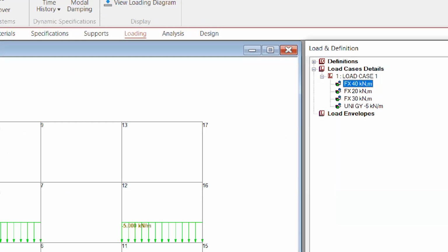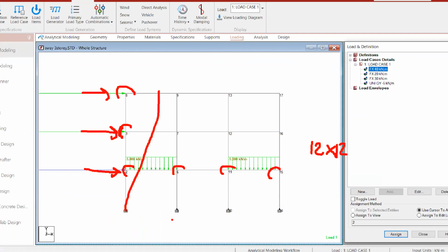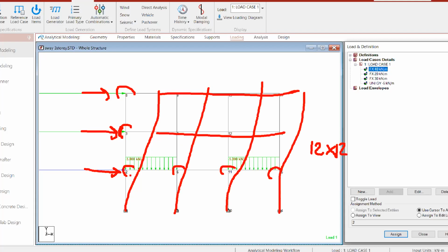Now you can realize that aside from the rotation degrees of freedom earlier, so this is 12 by 12, right? Because you have three rotations here multiplied by four columns, so that will be 3 times 4, 12. Now, since we have lateral load, we expect our frame to behave something like this. Therefore, we can now consider the lateral displacements.